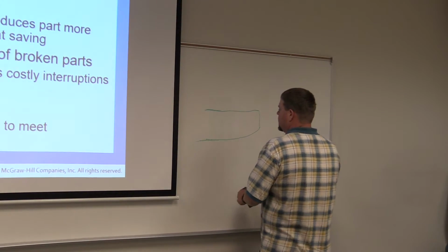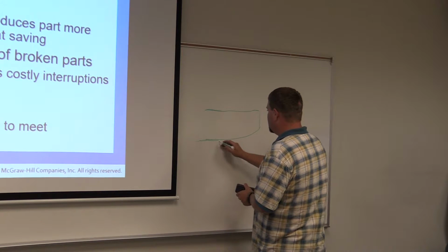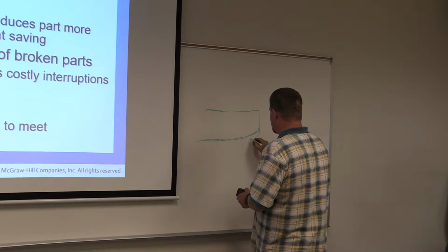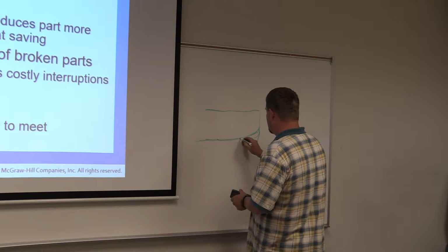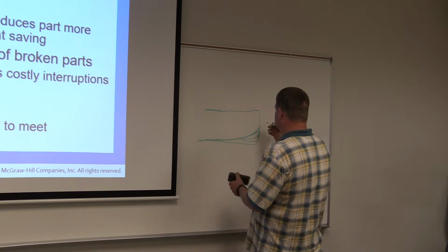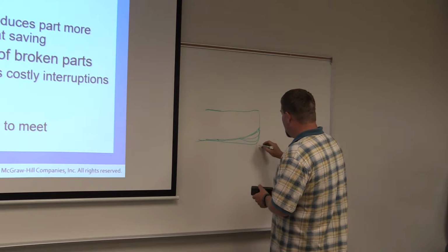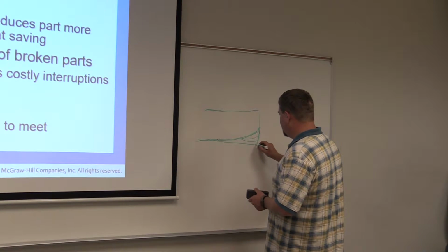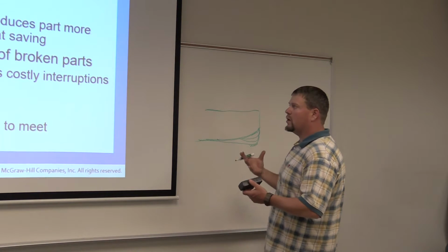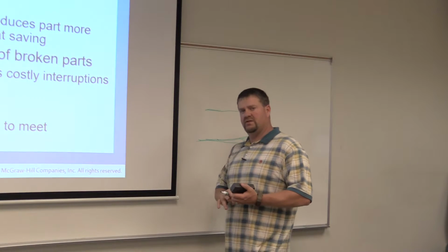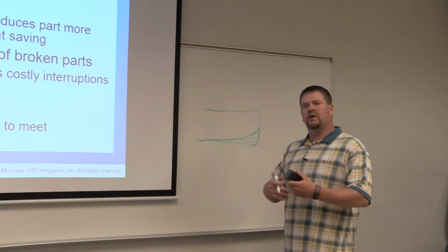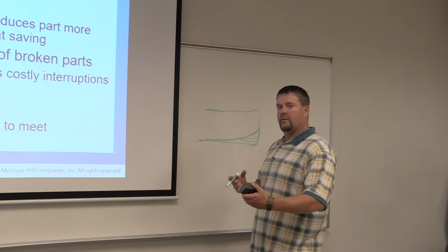However, as long as you maintain it, you could weld this back up to its original shape, and then come back in behind that and put a harder hard-facing material on it. A lot stronger hard-facing material that has some abrasion resistance, maybe some impact resistance, and so forth.